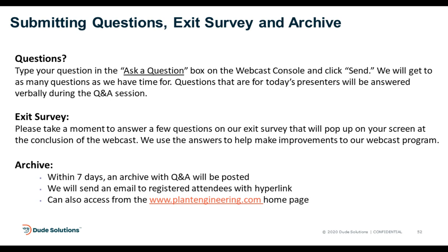So a good CMMS has been creating preventive and corrective maintenance work orders based on that type of usage and meter reading type data. It's just been done largely by a human typing in a value into a screen in the CMMS. Where we're seeing the biggest improvements is in the availability and the affordability of the physical world, the sensors. You really can't acquire a new asset anymore that is not going to deliver you some sort of electronic data, usage, alarms, and so forth.